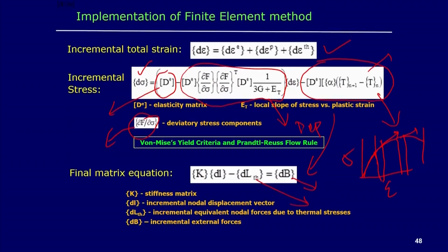Finally, once we know the stress distribution, or the principal stress components sigma 1, sigma 2, sigma 3, we can find the von Mises-Hill function, that means the average stress value following the von Mises-Hill functional form. All these calculations are linked with each other, and in this way we can find the strain and stress fields simply by predicting the displacement field in the simulation.